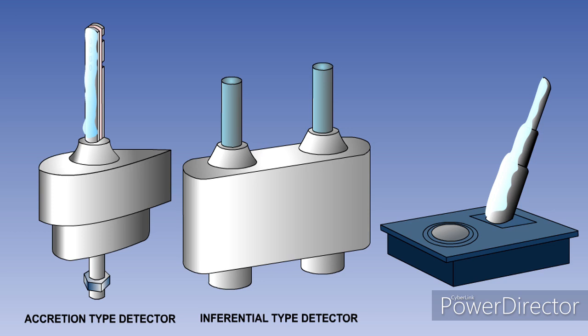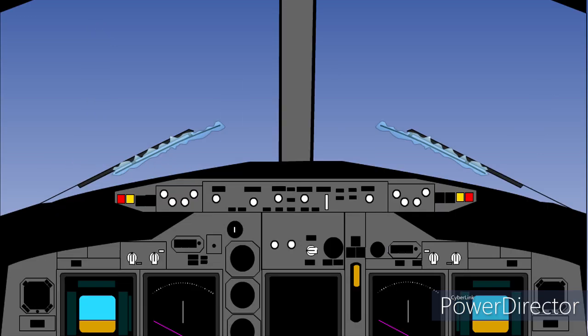You will find that on many modern aircraft there is no ice warning system, or perhaps just the Teddington type of visual indicator. So an awareness of the in-flight conditions with regard to temperature and moisture is essential for all aircrew. In icing conditions, the first signs of ice build-up can usually be spotted on aerials or on the windscreen wipers.